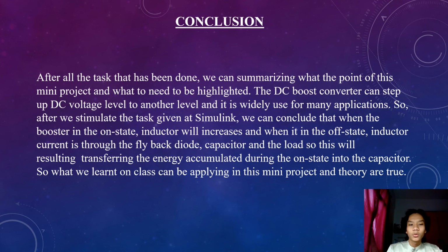After we simulated the task given in Simulink, we can conclude that when the boost converter is in the on state, the inductor current will increase, and when it is in the off state, the inductor current flows through the flyback diode, capacitor and the load, resulting in transferring the energy accumulated during the on state into the capacitor. So what we learned in class can be applied in this mini project and the theory is true.